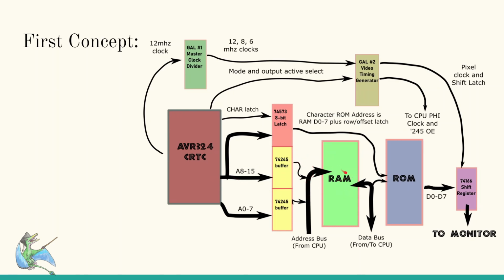That would put the address of the character buffer onto the RAM chip, and then the output would come out of the data bus on this side, and the ROM chip would be hanging there. So these would be the address lines of the ROM connected to the data bus, and then they are combined with the contents of this latch, and that produces the data byte, which then goes into the shift register.